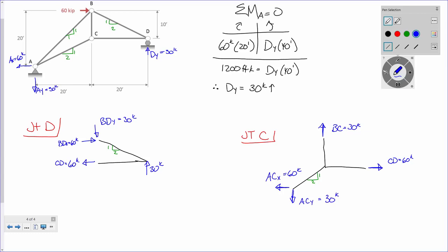If you solve for the angle and then take the sine of that angle, or take the cosine of that angle, you're doing more number crunching. You know what this slope ratio thing is? This is SOHCAHTOA. Opposite over hypotenuse, adjacent over hypotenuse. This is tangent, opposite over adjacent. That's what a slope ratio is. So that's why I do it that way. I think it's a whole lot easier. Yeah, and it is. AY is 30 going down. So you didn't even have to do any equilibrium. You just look at it.